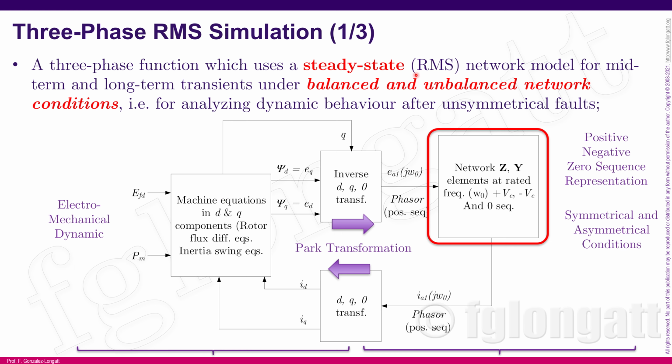That means that we can use this admittance or impedance matrix, okay? And these kinds of studies are quite common, to be honest. Also, that is one of the classic mistakes of rookie users of PowerFactory, that they try to use positive sequence to run the calculation for a single line fault. And then when they get a ground result, they start to scratch their head.